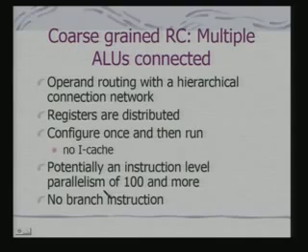Then we can have coarse grained reconfigurability. We have got simple logic gates, putting together logic gates to realize simple logic functions. From there you can have a set of ALUs, and you can now configure these ALUs and a set of registers to do some tasks. So it becomes an example of coarse grained reconfigurability.